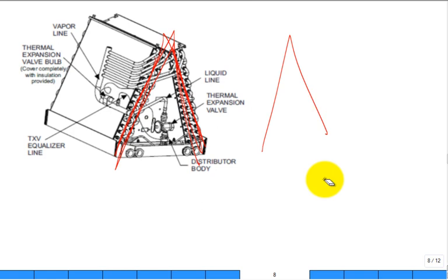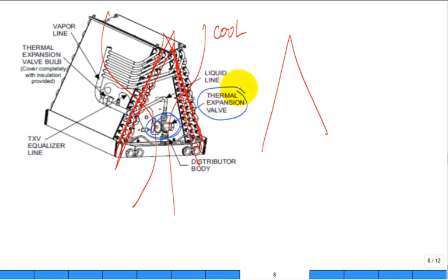It's an A coil. And airflow comes up and goes this way across the coil. It's warm and it comes out cool, and then it gets distributed to your house. And right here is a thermal expansion valve. That's a metering device. Okay, it's a throttling device. So they're all over. In the automobile, I have one upstairs. I was going to bring it, I forgot, and I could pass it around. Some students said, I work in shop, here's one. You can use it as a demo.